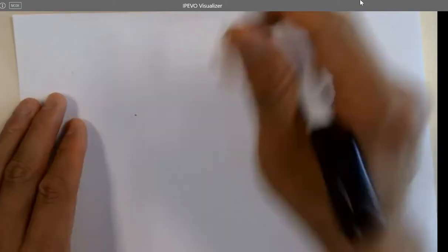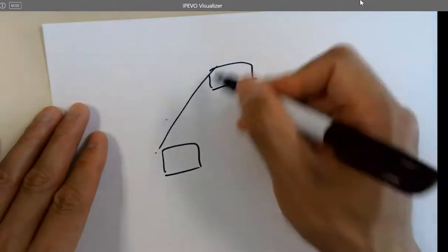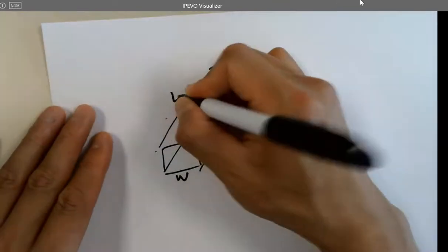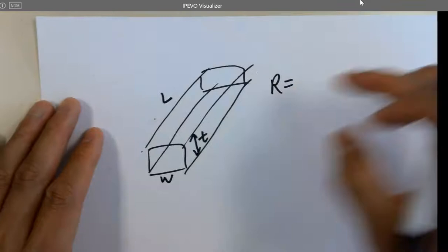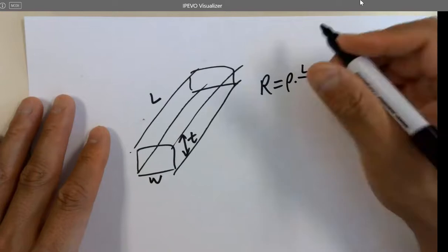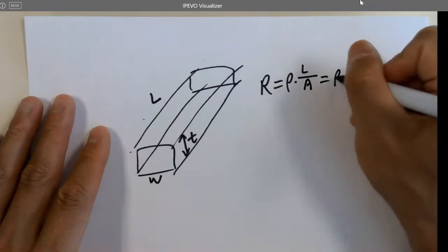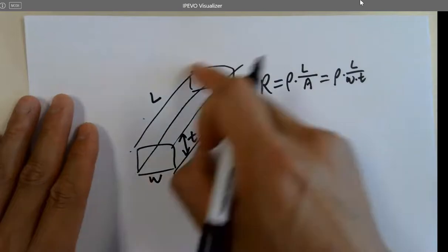And next, we were talking about the resistor, the n-well resistor. It's a 3D structure, even though it looks 2D on the paper. Like that, okay? So that's the n-well resistor. That's the width of it, that's the length, and that's the thickness. The resistance of the resistor, not just for n-well but for all other materials, is the resistivity times L over A, where A is the area. In this example, it is rho times L over W times T. That's the resistance of this n-well.